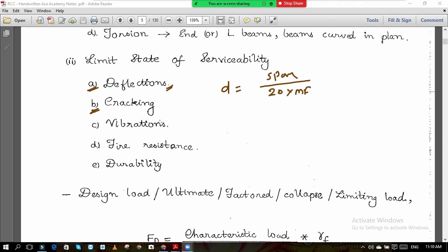Then vibrators, you know, needle vibrator. Then for large structures, compaction is done by vibrations also, and vibration loads are also there. Suppose now a long bridge is there, and on that bridge a truck is moving and that truck is having 30 tires. Okay, in that case it is a moving load, no doubt, but some vibrational load is also acting on that structure. Okay, that also comes under this limit state of serviceability.